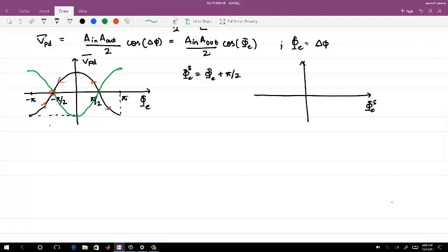It will become more clear when I translate this phi e to phi es, that you will see a slightly linear slope at phi es equals 0, which is nothing but a mathematical way of representing it. Okay, I can do all the analysis at this point itself. There is nothing stopping me. This is just another way to say that I lock to a zero steady state phase error. So if I just shift it by